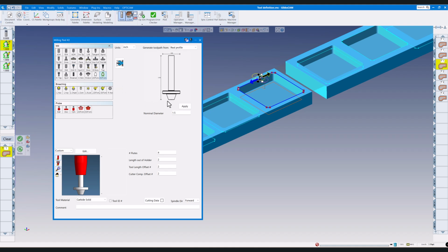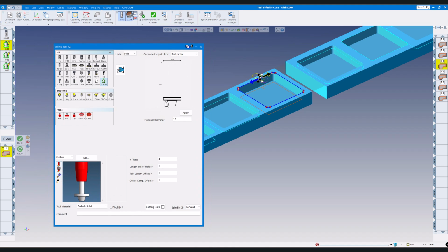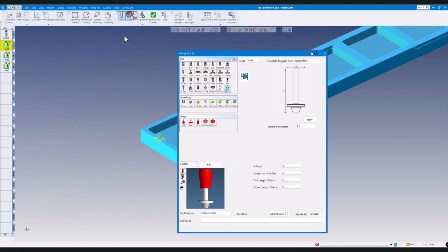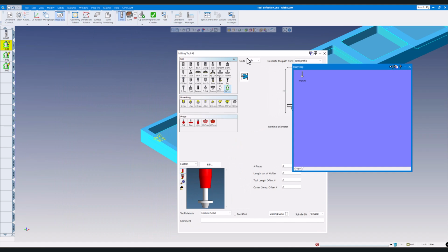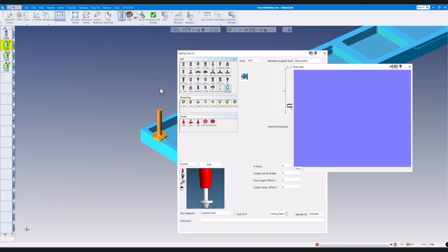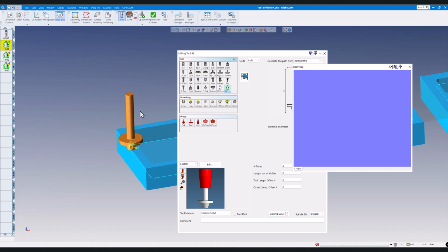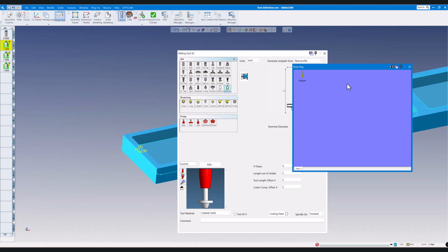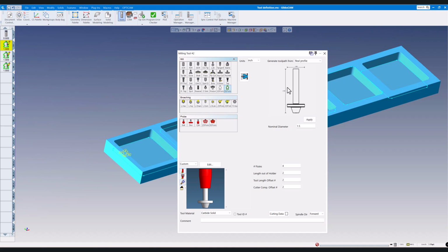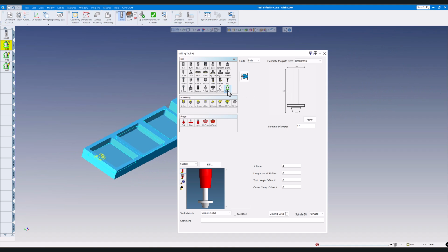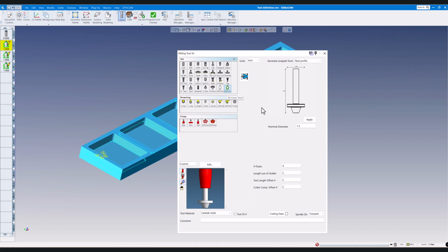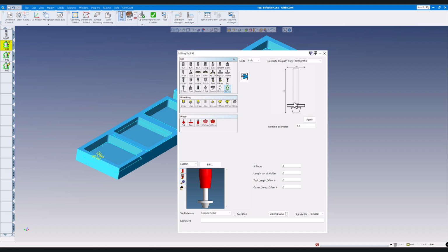This is what my form tool looks like. I showed you a picture of that a little earlier. But this is what the tool looks like. I have a solid model in my body bag here. Let's bring that out. There's my form tool that I showed you before. Let's put this back. So I clicked on Form Tool, 3D Form Tool, said Apply, and it drew the part.